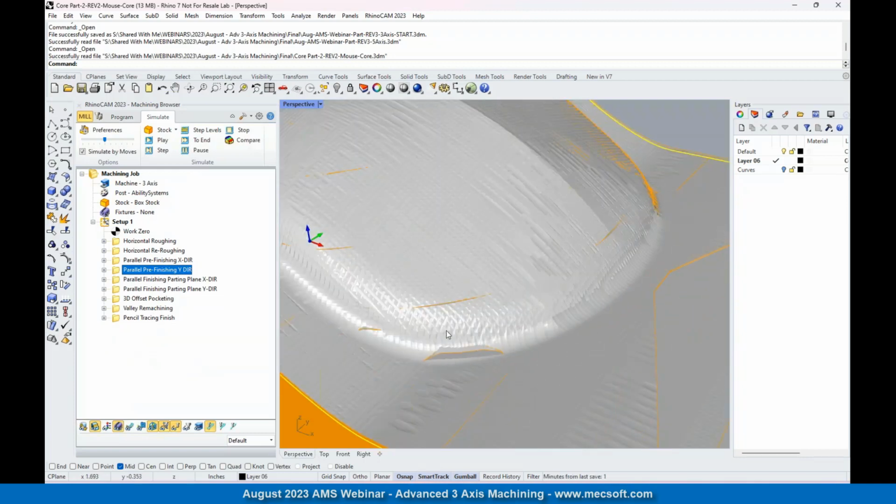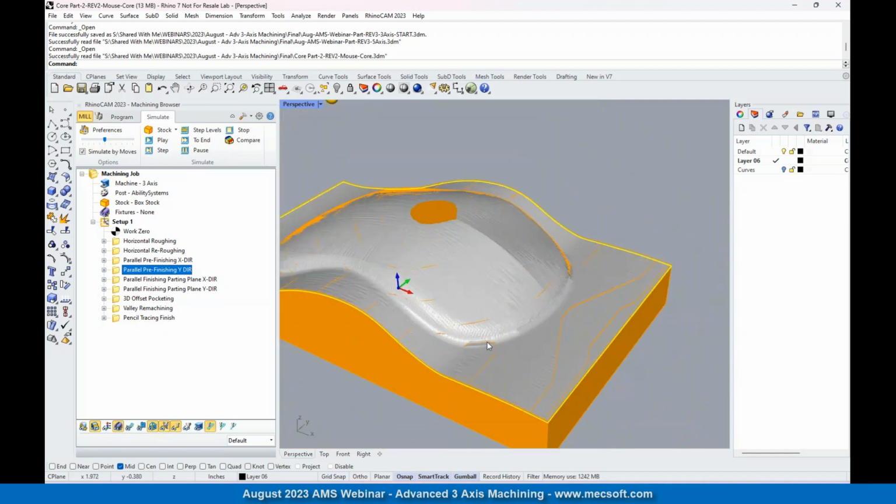part had no fillet and it had no draft. If you have a fillet at the bottom of your part and it also has a draft, use a tapered mill that has the same draft angle and the same ball radius on the mill, and it'll cut those for you.